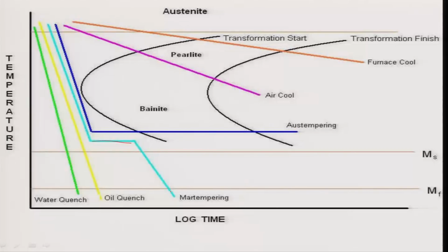Okay. On a lighter side, this is what I can say, because we can take the same composition of steel and change these heat treatment parameters, we can generate different microstructures, and by different microstructures we can have different properties. And that is our end game, right. You want to have properties of the material which are useful. So, to obtain that, we simply have different cooling rates, different environments, different ways of changing the microstructure.